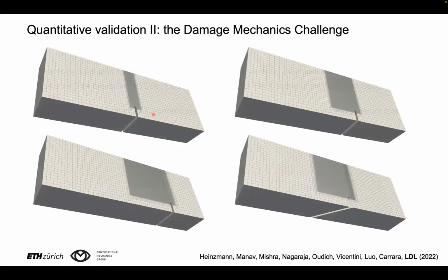Here you see the finite element mesh for the 4 specimens involved in the calibration phase. They're basically all 3-point bending tests with notches. Here we have a centered notch. Here we have an offset notch and another offset notch with different distances from the center. And here we have a skewed notch. Plus there is one additional specimen for which one has to perform the blind prediction.